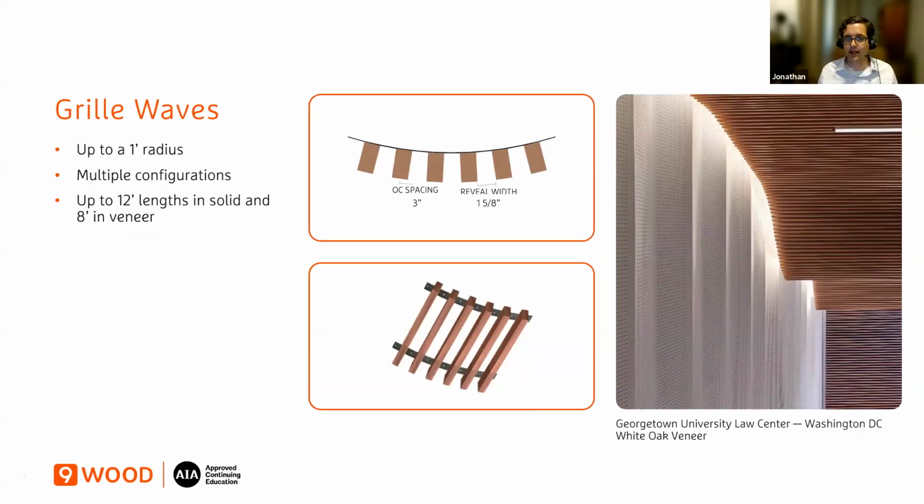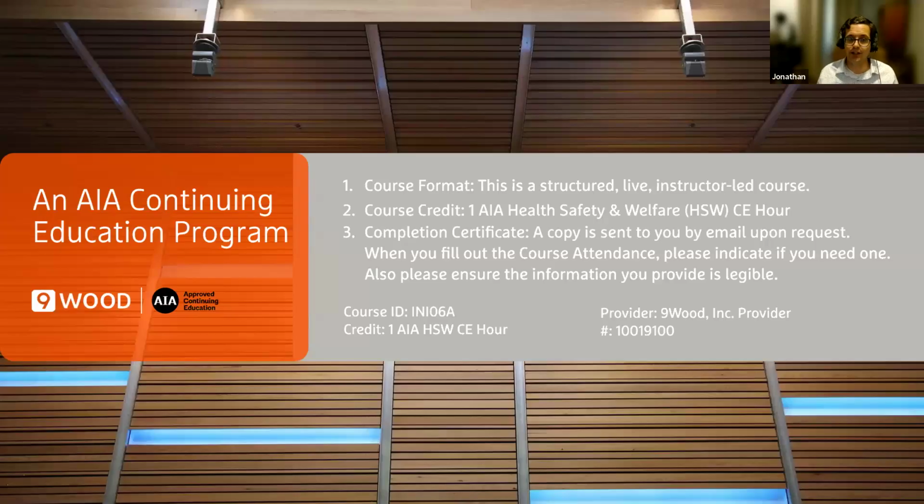It is available. There are parameters that are important that you'll need to find out from the manufacturer. So if you have very deep member grills and a tight radius, it can segment and maybe look funky. So just find out what the best parameters are to achieve that look and get samples, and ideally look at some photos of installed spaces with what you're looking at so you can see the end result too, and make an informed choice there. Well, that's the CEU.